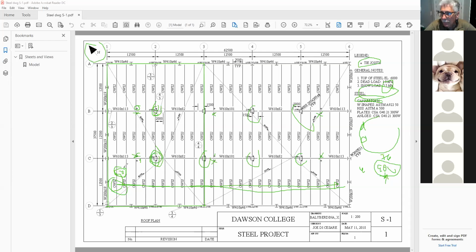Sir? I have a question about what we did last week. What did we do last week? With the vertical brace connection. Okay, so we didn't do anything about the gusset plate. Do we have to do the welding of the gusset plate and the size of the gusset plate? Everything, yeah. You've got all that information now. You should be able to size the gusset plate, how much welding is required, and then you have to connect your gusset plate to your structure. Okay, so we just do it the same way like we did the plate? Yeah, the plate that's connected.